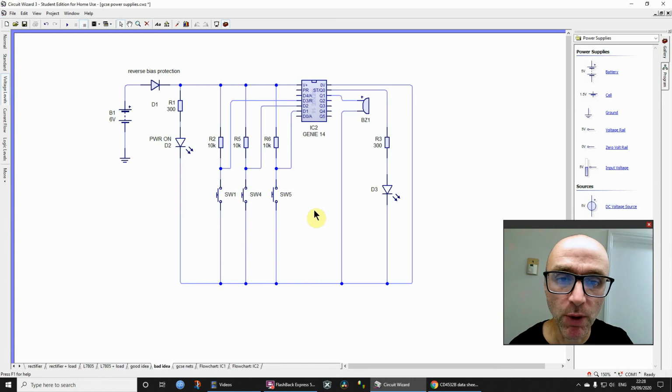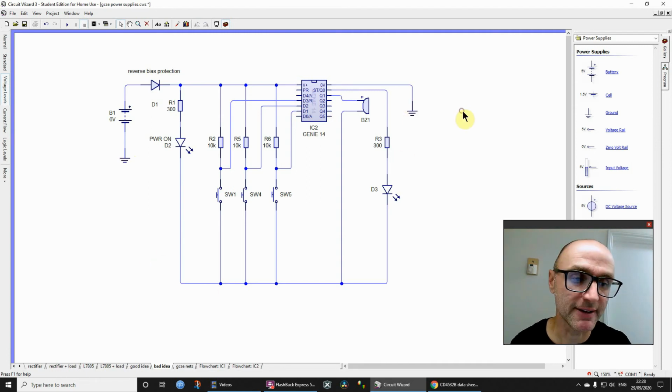So we cut out that wire there. Let's cut out some other unnecessary wires. See, that's 0 volts there. So now I'm going to press and hold control and then drag that, and I'm going to have it like that. Okay, so now effectively I've got a connection of 0 volts from there to there.